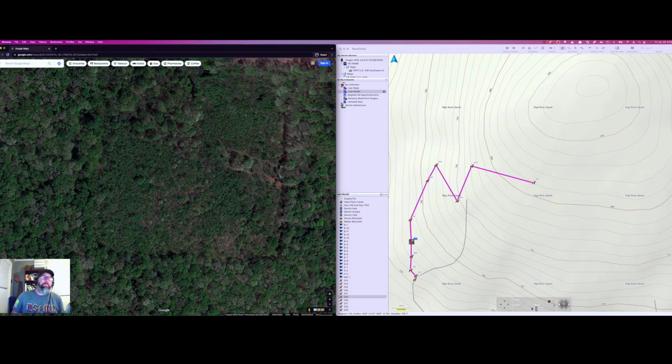So because we hit the rock outcropping when we were drawing it, I saved some more waypoints on the GPS, plotted it out again, and realized we're about 15% slope. And so I had to lay it out with 2 switchbacks instead of 1. And then that gave us less than 10%, based on the grade. And I'll show you how I did that.